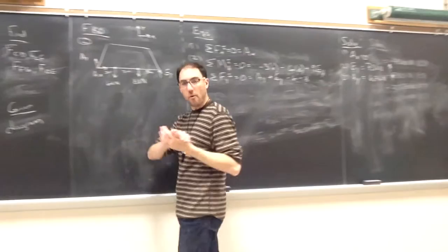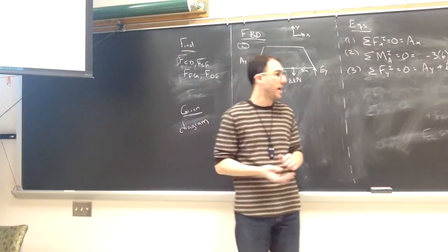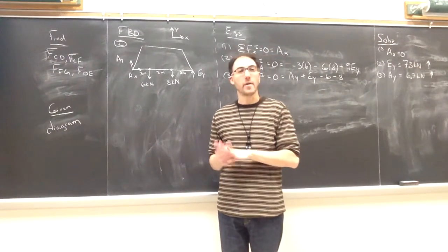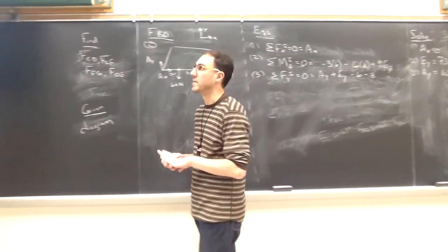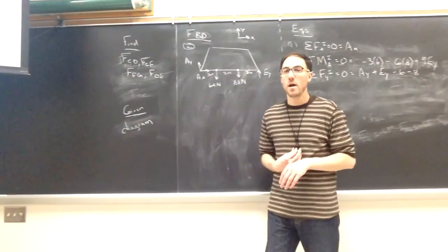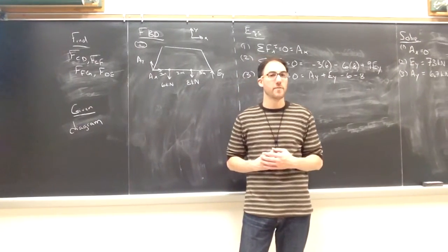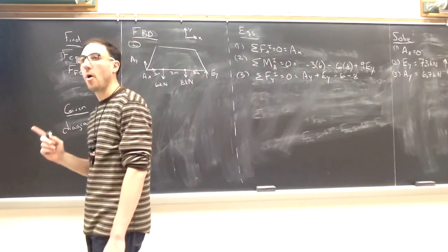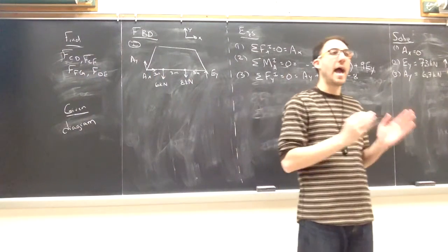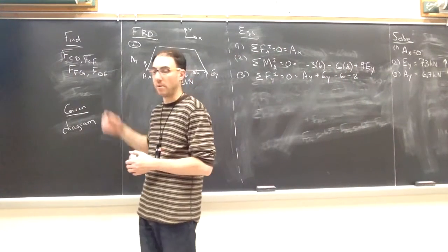Right, so again, before we even decide, do we want to make a section cut, do we want to make a pin diagram, we want to look at our system and see, is it statically indeterminate or statically determinate? If it's statically determinate, we're almost always better off making this external free body diagram and then solving for those reactions. Almost always, I would say, do not cut through more than 3 members and try to cut through as many members that you ultimately want as possible.